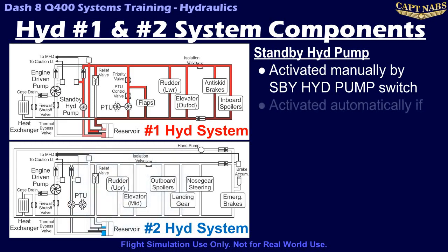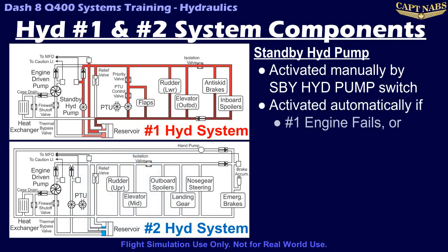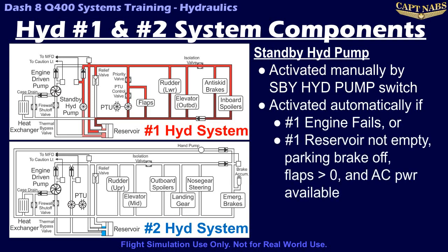The standby pump is also automatically activated if the left engine fails, or the number 1 reservoir is not empty, the parking brake is off, the flaps are greater than 0, and AC power is available. For this second condition, these conditions are normally met anytime the aircraft is taxiing, taking off, or landing. This automated system ensures sufficient hydraulic pressure is available during critical flight times.